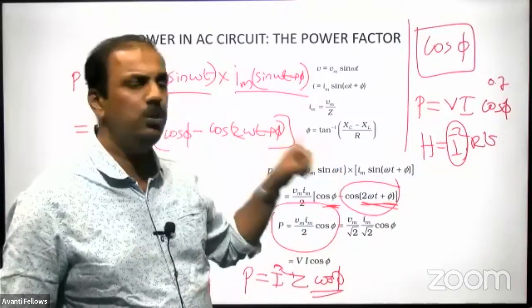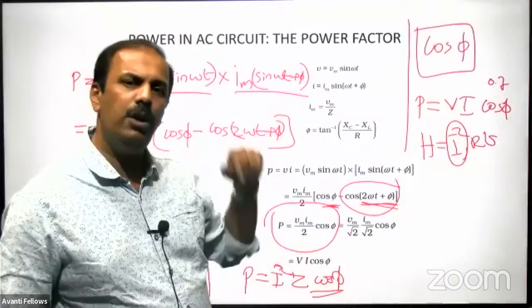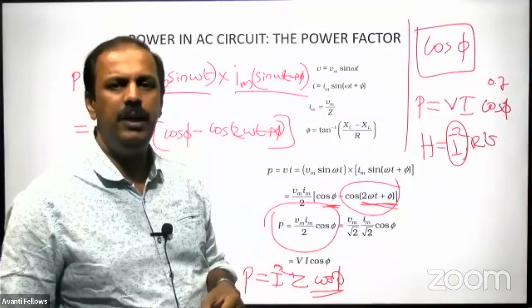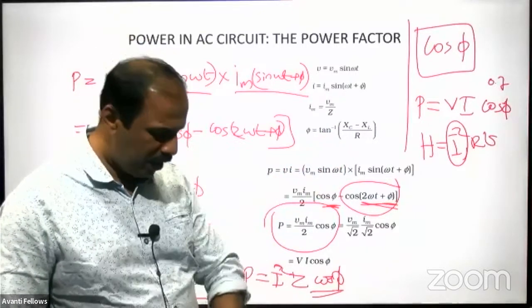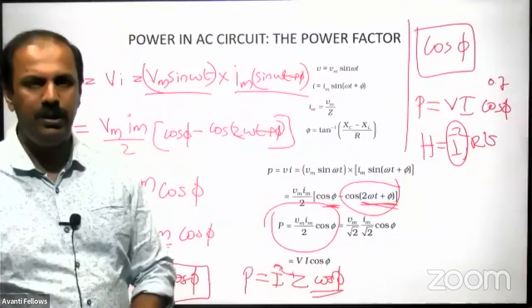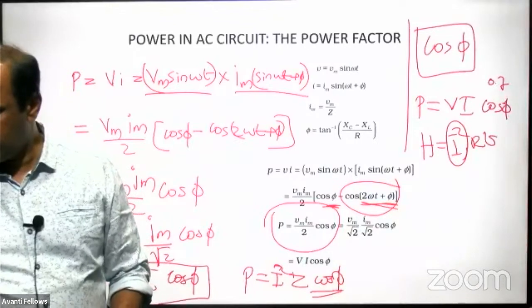Power factor should be 1. If power factor is not 1, transmission loss will be there. If you want to reduce the transmission loss, we have to add additional capacitors. Okay, so that's about this power factor.